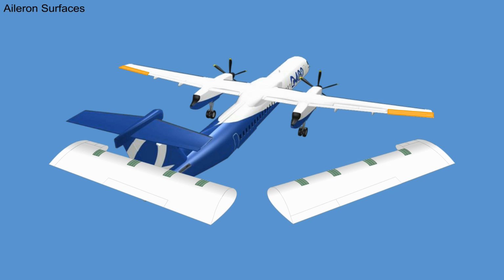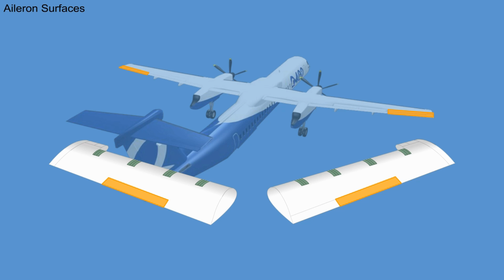There are two aileron control surfaces installed on the outboard end of the left and right wings. Each aileron is attached to the trailing edge of its related wing by 4 hinge fittings. A horn with internal mass balance weights is located on the outboard end of each aileron to give aerodynamic balance. Each aileron has a geared tab, which gives aerodynamic assistance to the aileron control surface. The aileron geared tabs are attached by 4 hinge fittings to the trailing edge of each aileron.